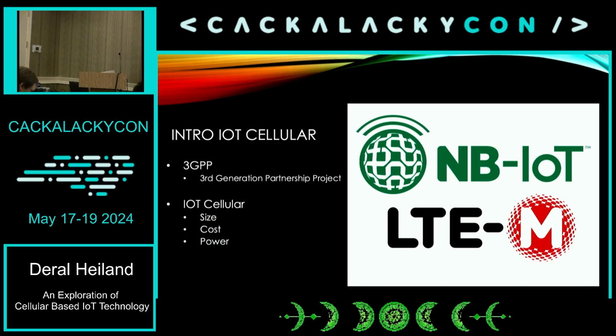Then we get into power. Power consumption is always an issue because you're dealing with devices that may be battery operated. If you transmit data and consume a lot of power, you're going to drain the batteries quickly. These devices fall into those categories. There are two general types of devices we call NB-IoT and LTE-M, and there are a couple of different versions of each.